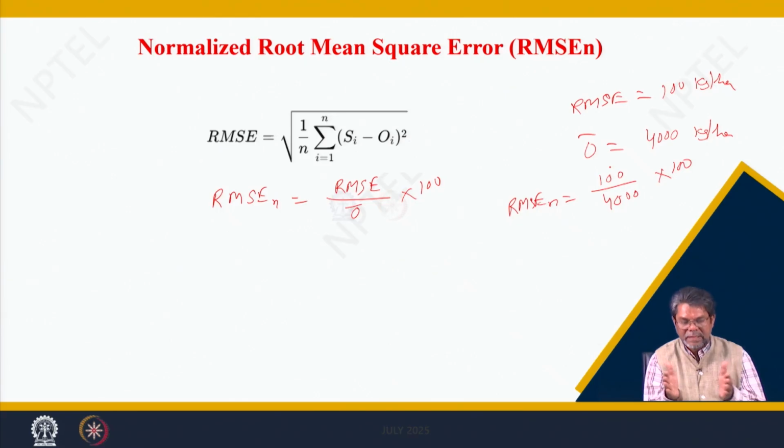If they are the same, then the RMSE becomes 0, because the simulation value becomes the same as the observed value. So, there is no error, root mean square error becomes 0, but in reality this never happens. So, there is some error, and we need to calculate it. How much error? That will guide us on how to go for the calibration of the model parameters to have a best match, best fit between the simulation and observed output, so that we can minimize the error. The idea of calibration and validation is to minimize the error in the model.